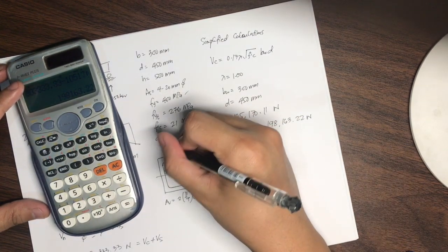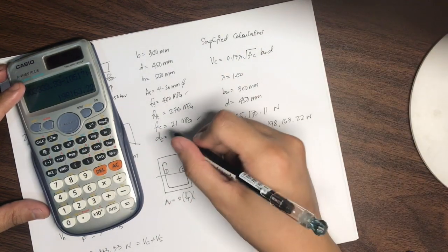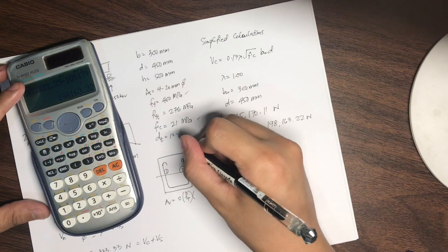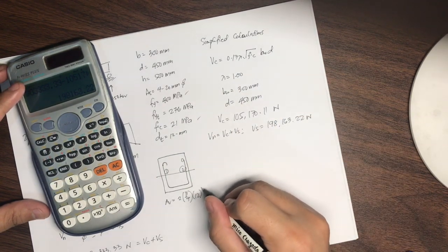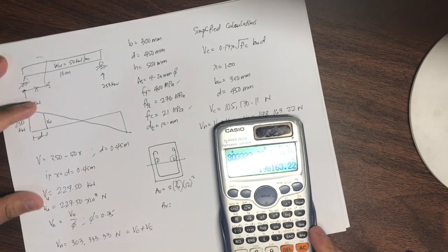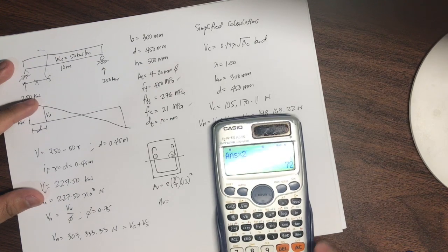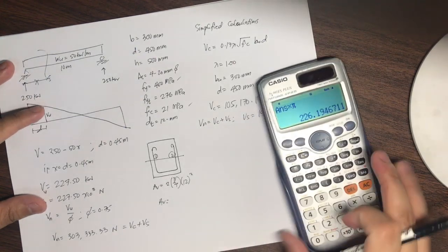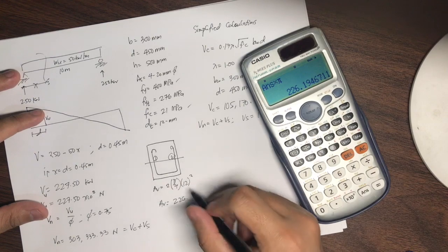Let's say the diameter of the transverse reinforcement is 12 millimeters. So I have here 12 squared. So Av is just equal to 144 divided by 4 times 2 times pi. So that will give you 72 pi, or 226.19